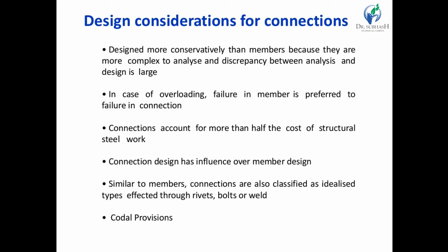Now design considerations of connection. Which parameters should we keep in mind for designing? Connections should be designed more conservatively than members because they are more complex, and the gap between analysis and design is large. In case of overloading, failure in the member is preferred to failure of the connection. Connections account for more than half the cost of structural steel work, so connection design has influence over member design. Connections are ideally effected through rivets, bolting or welding.